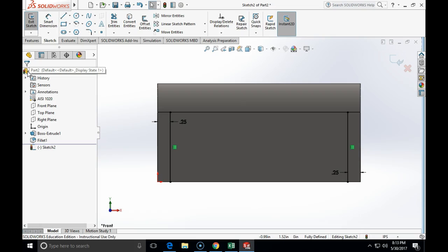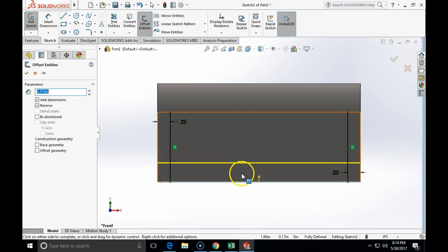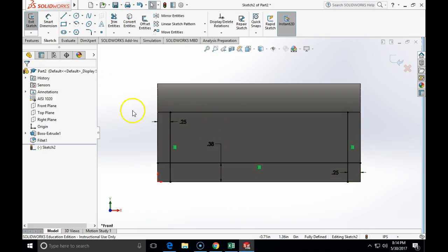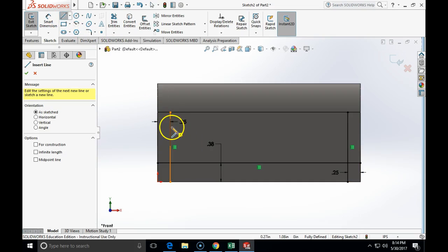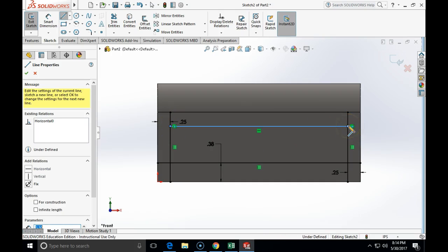It's correct. The bottom is offsetted for a 3/8. So I will click on an offset, type in 3 divided by 8, click on a bottom line, and click reverse to get it offsetted up. Now I need just to calculate or to determine the one more. And we know that 1 3/8 distance will be from our last line. So we will place the last line.